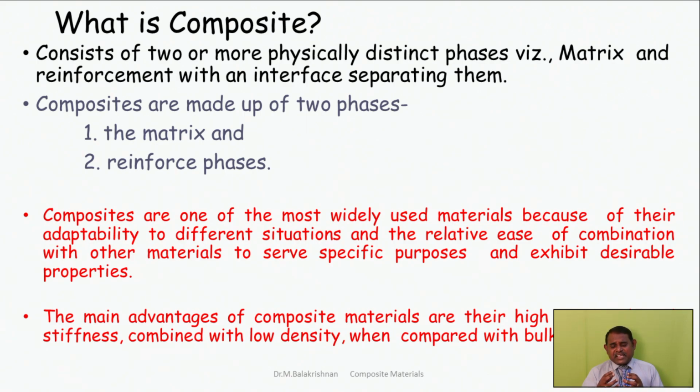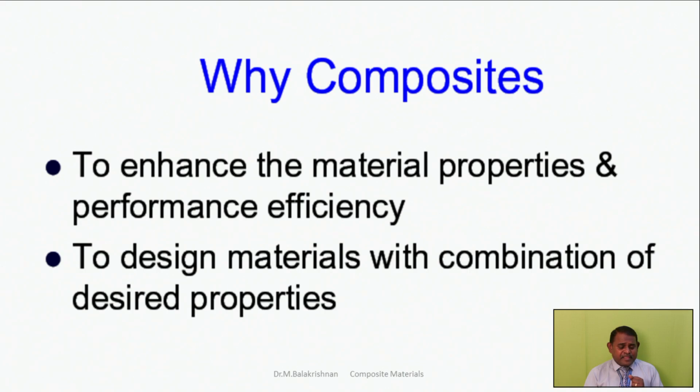But the same strength can be easily achieved by composite materials like aluminum alloy composite when it is added with silicon carbide particles. It can give 650 or 700 megapascal strength, even for a pure aluminum alloy. So this gives one third of the density, one third of the weight, and I can go with the high strength. So that is the beauty of selecting composite materials.